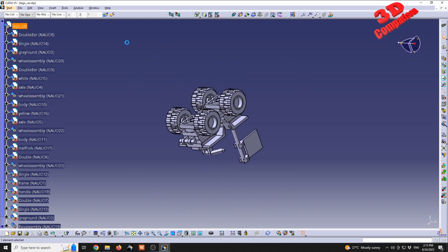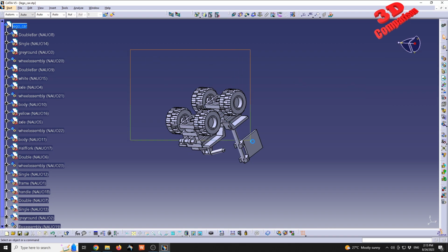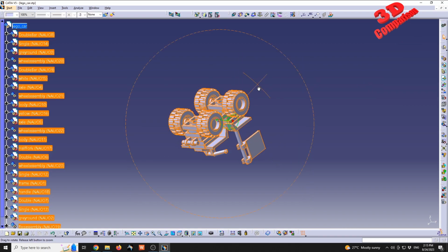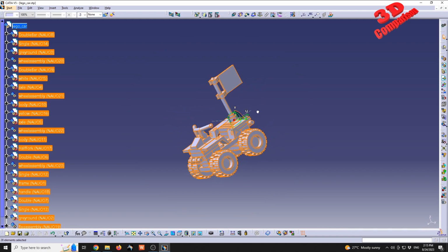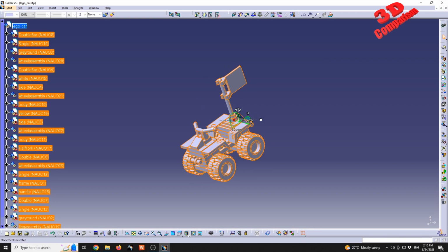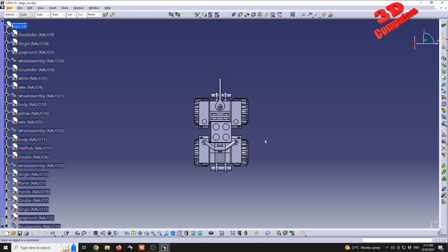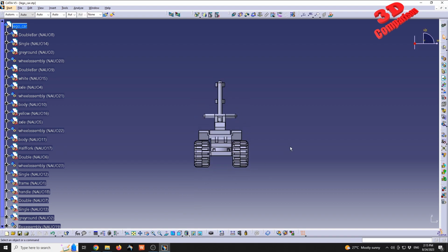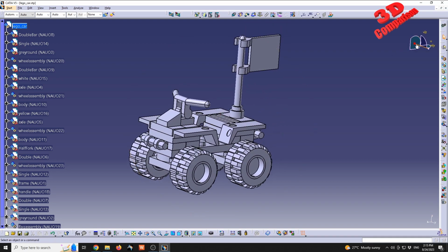So in order to fix that, just select again. The last snap automatically to selected object is still active. That means we just need to select the model, and afterwards rotate it on the same axis, so it will be this axis, and I'm going to snap this to 180 now, because we saw that initially we didn't properly align. Now this will be the top view. If I go for the front view, it will be the front of the car. So that is how you can manipulate and orient objects within CATIA V5.